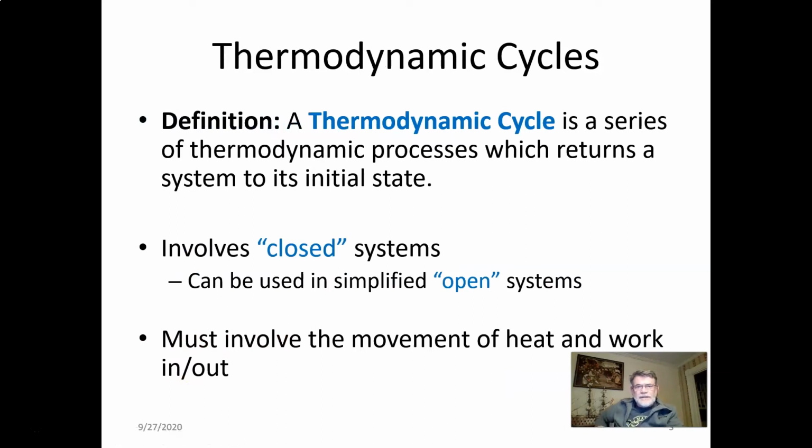So what is the definition of a thermodynamic cycle? A thermodynamic cycle, as you surely guessed, is a series of processes which return the system to its initial state. So it's like a loop. You start in one state, go through some processes and come back to the exact same point. So there are two main families, the closed cycles and the open cycles.